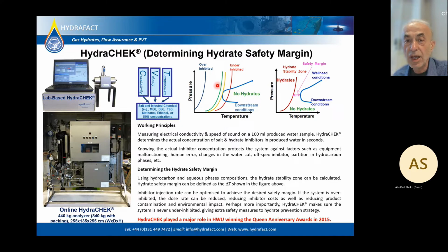So if it is here, it's ideal. But in most cases, we are here. Even in the beginning, with time, reservoir pressure will drop and the risk of hydrate is less. But most companies will follow the original inhibitor injection.